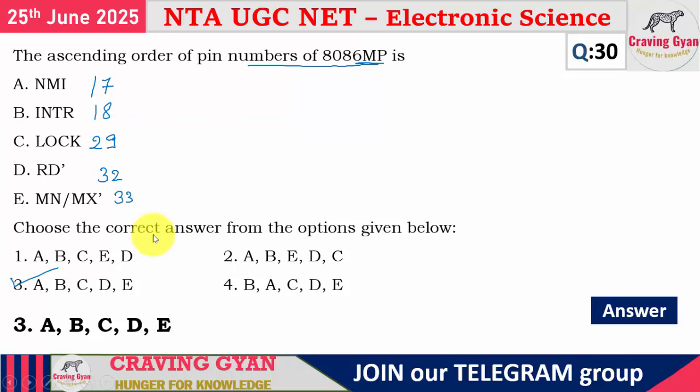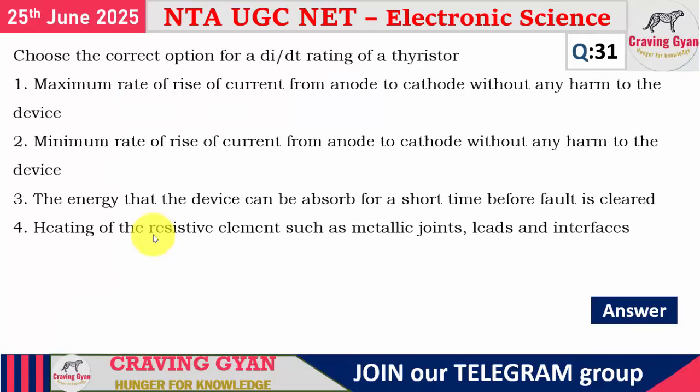See what sort of question they have given. We have to remember the pin numbers, it seems. What is the correct option in the case of dI by dt rating of a thyristor? See, you will be having snubber circuit protection: dI by dt protection, also referred to as overcurrent protection, and dV by dt protection, also referred to as overvoltage protection.